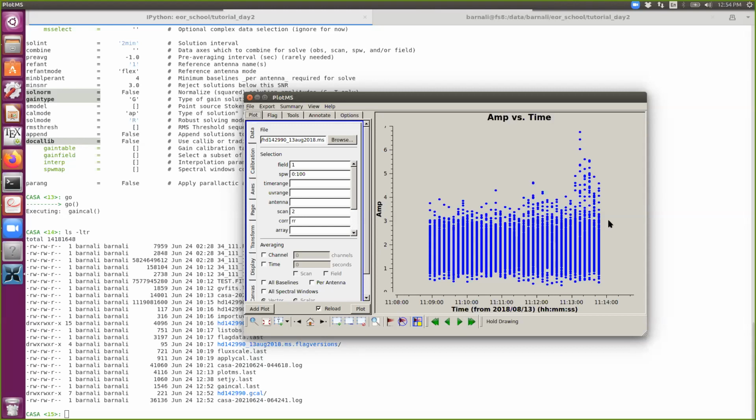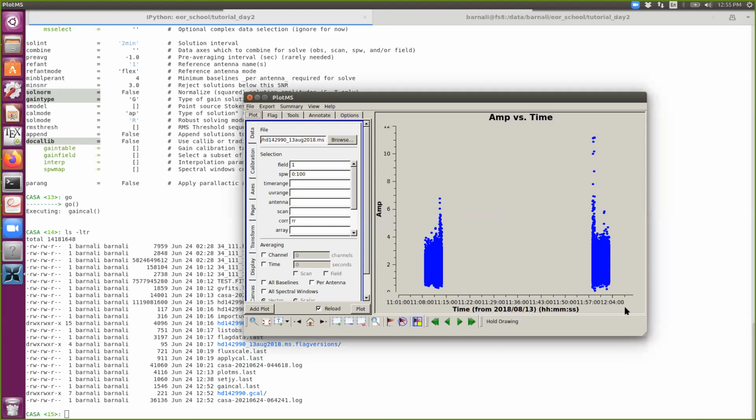When we do the phase calibration, we rotate the antenna to our phase calibrator, that is done after this 15 minutes interval, right? Yes, you are right. We do the phase calibration at 11:09, and the next one at 11:14, something like that. Yes, within this 15 minutes time interval, which is my scan interval.